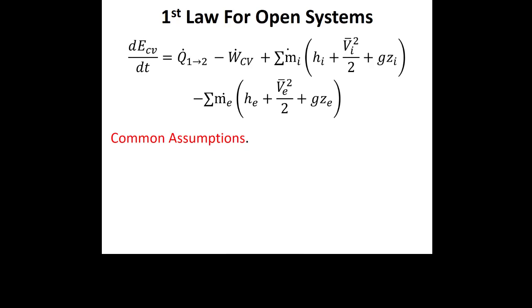Okay, so that's great, right? We know that we're looking for W.net over Q.in, but how do we get W.net and how do we get Q.in, right? This comes down to that second question, right? What happens to the mass? And we know that we're talking about open systems as we move through the cycle here, right? So, systems will be at steady state, right? They're always one inlet, one outlet, or at least we never split the mass in this particular cycle.